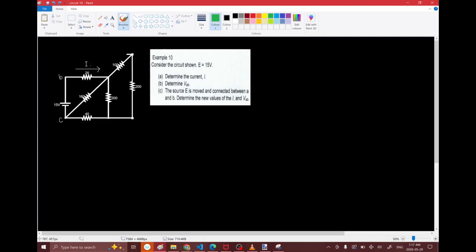Okay, so continuing on, it's the total current of the battery. So whenever a question asks you to find the total current of a battery, like the total current coming out of the battery, usually what that means is that they want you to find the total resistance of the path of the circuit, I mean. And using that, you can figure out what the total current is going to be. So let me show you. So first thing is, let's find R_T, the total resistance.